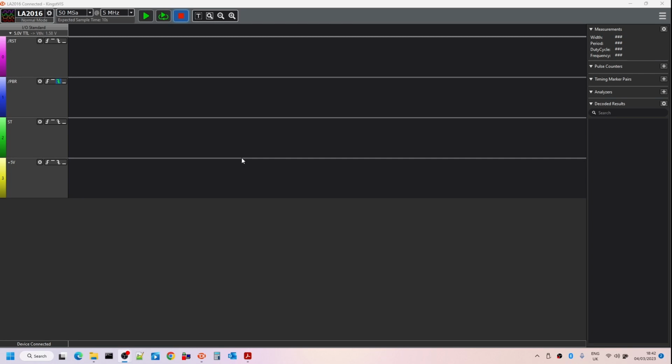So what I've done now is I've disconnected the ST signal, so there's no longer a clock signal telling the supervisor circuit that the processor is alive. And what I can see at the moment is the Nanocomp display keeps flashing on and off about every second or so, so it's being reset on a regular basis. So I'm just going to quickly press the reset button, and we should be able to see the processor being reset once every second or so by the watchdog supervisor circuit.